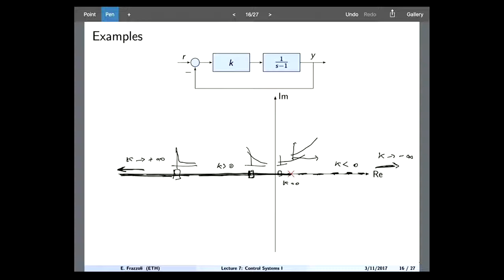At some point, you're a great controls engineer, you're very confident, you do your thing in MATLAB or whatever. At some point in your life, you will get the sign wrong, okay? So now you are convinced, so I choose my gain to be, say, +2, so that will place my closed loop pole, say here. Then you do your coding, and then you forget, you make a sign error. And now instead of having your gain at +2, you have your gain as -2.